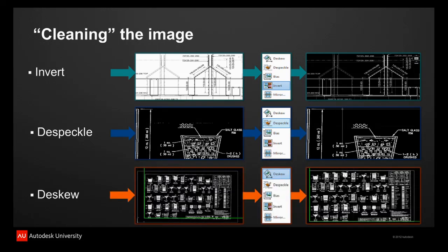All right. The next one is to de-skew, and this is quite a common one. As you saw with my lesser quality image, this one is obviously scanned in, and it wasn't scanned perfectly. It was actually a little bit skew. And the de-skew command works very much similar to what the alignment tool in AutoCAD works. Right. So when you select de-skew, it will ask you to specify a base point. It will ask you in the X direction to specify an existing point.